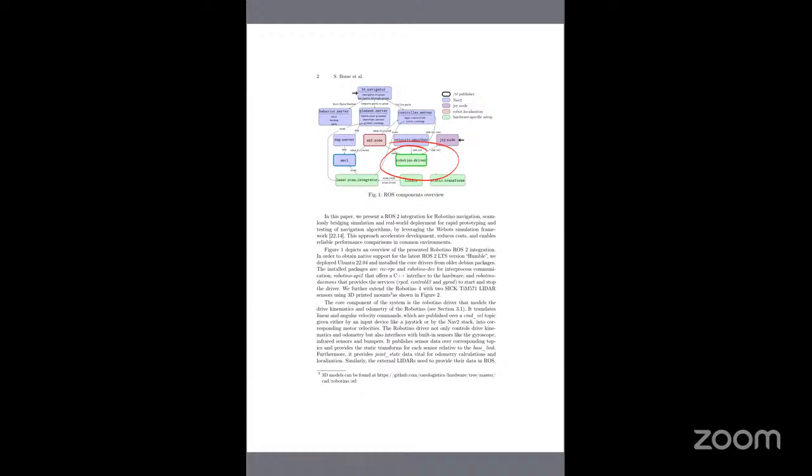So the Robotino driver will change this to motor speed. For cmd_vel, we have two sources, right? One is the joystick, cmd_vel, Robotino driver. Another is Nav2: navigation goal, planner, controller, cmd_vel, Robotino driver. So cmd_vel, inverse kinematics, wheel 1 speed, wheel 2 speed, and wheel 3 speed.